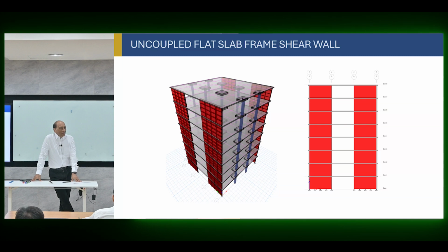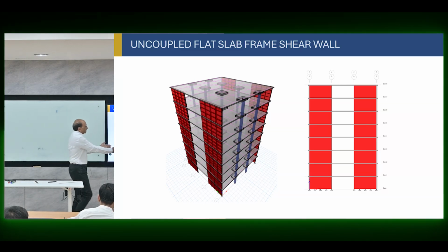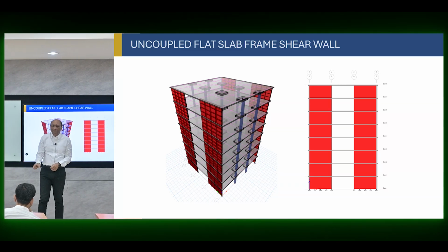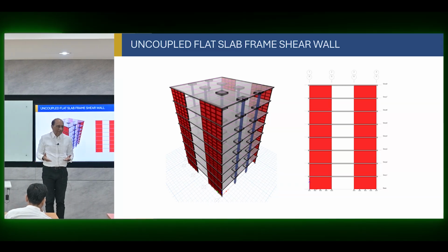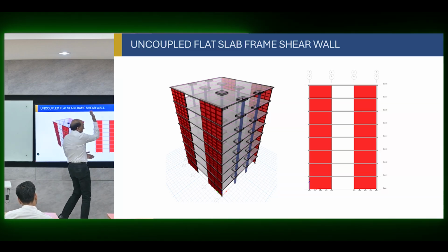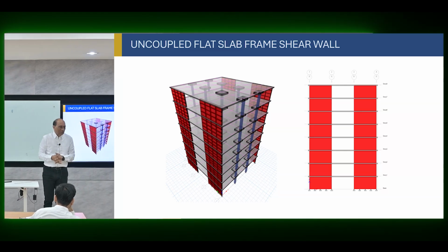So there's a limit on how tall you can go on this one, because walls as cantilevers cannot go too far unless they're coupled. You cannot find this limit exactly. It depends on the size of the wall and many things. So it's a cantilever. Typically for one wall, you cannot have more than a 1 to 12 ratio, height over width, 12. Which is not good, because if the building is, let's say, 100 meters, you need 10 meter, 12 meter walls to do that, right? So that's not always possible.